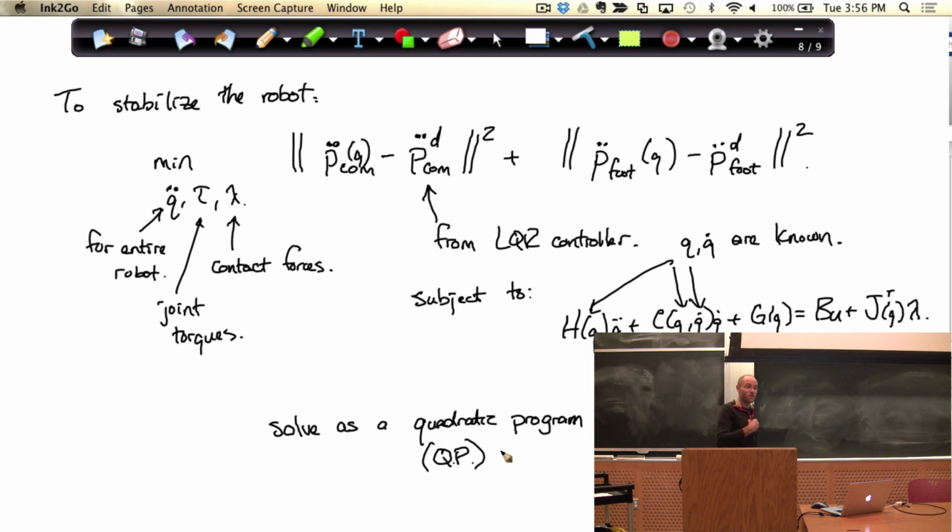Although Tuan, who's up there, has a really nice paper on capture point that I'll cite in the notes, which has really nice mechanical insights about that and helps you get your head around that picture. And you could imagine running Robin's footstep planner fast enough that it runs online and get something like that out. It's really hard. I still think the satellite problem with moving thrusters is not solved to my satisfaction. But if you're willing to prescribe the trajectory of the thrusters with a heuristic like this, then reading out the motion of the satellite works. Good. It turns out that story is going to generalize very nicely into manipulation, thinking about contact forces first, and we'll talk about that on Thursday.